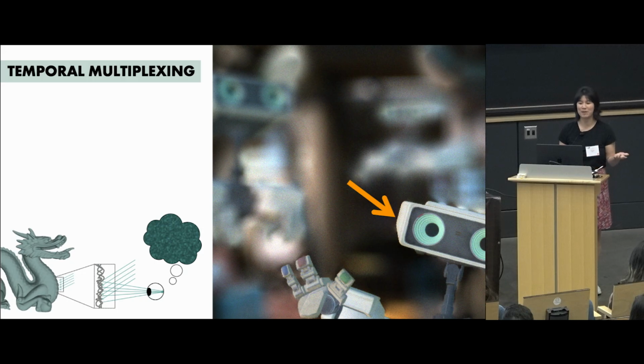Also, as Mark mentioned, our speckle reduction is going to go with the square root of the number of frames. So we start to get diminishing returns if we want more speckle reduction than we can get. And we really run into a data bandwidth problem. We might have 1 million, 2 million, 4 million pixels on our modulator, and we'd like to run this in the kilohertz range, maybe even tens of kilohertz. So that starts to be a lot of data that we're trying to stream through for these systems.